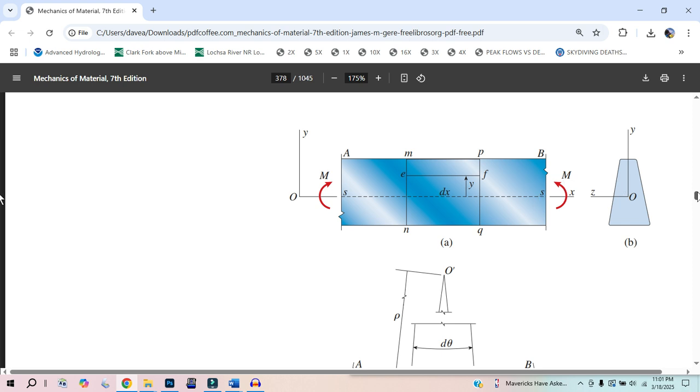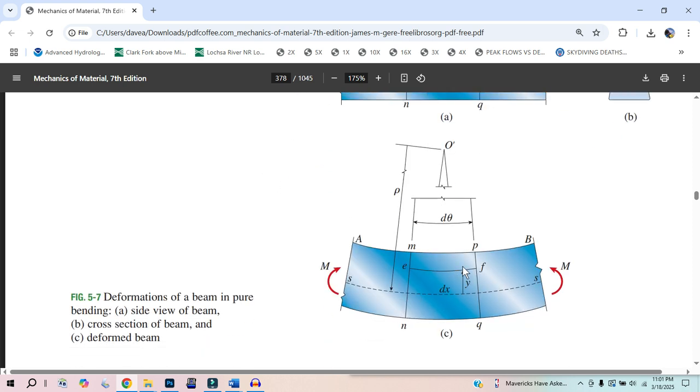And then we get a curvature, and it's going to be pure bending, in that plane. So all those things, cool. We're kind of covering our bases. And what that last sentence said is that up here, your strain is going to be great, and down here, your strain is also going to be great. With stresses and strains, you have to keep in mind that it can be a large positive number or a large negative number, and both will cause a failure of this part.